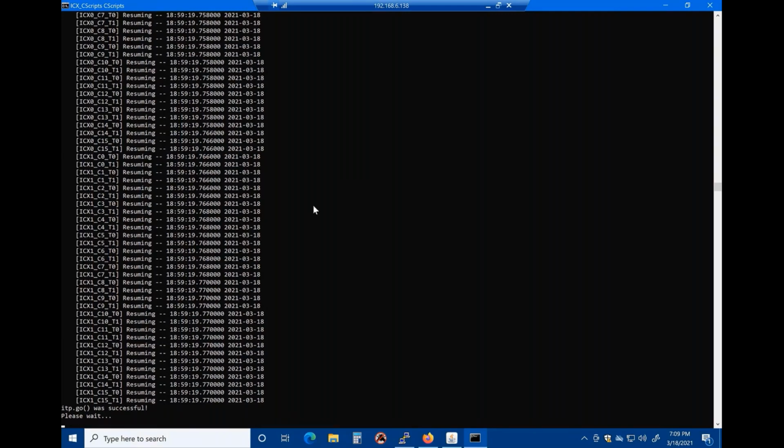Then it's going to go out and pull out the machine check architecture information. Then it's going to get the table of requests, or TOR dump data, associated with the caching home agents. And when it's finished that, it's going to get a bunch of other things, power management information, a big core. And then ultimately at the end, it's going to dump out all of the uncore information as well. And that takes a large amount of time. So you can use the C script in this instance when you're not in a hurry to get the platform up and running.